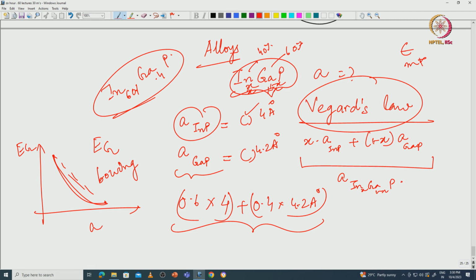It also depends on the method of growing, the way you grow some compound in MOCVD or MBE, the band gap could change, and whether you are measuring the band gap using optical method or electrical method, it could give different results. So, that way there is a lot of complexities there, so it does not go linearly as much, okay.